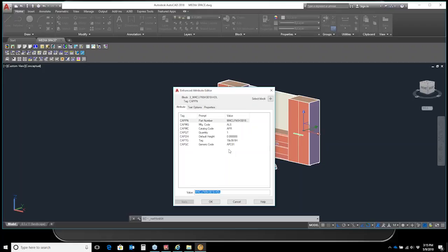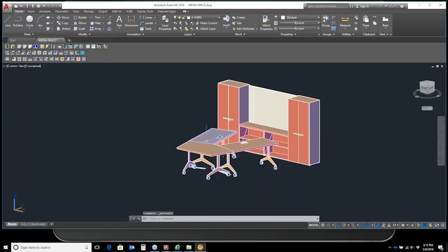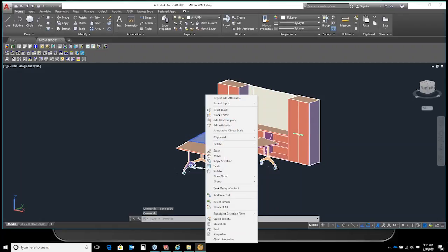So these are all important because in that nice data set that the manufacturers provide us, it basically contains the mapping information and all the assets that are required to producing that symbol in kits. Okay, so in case you're wondering why maybe a particular item isn't importing or a typical isn't importing, and you have access to CAD, if you actually click on one of the items and then you do a right click, you can look at the attribute.